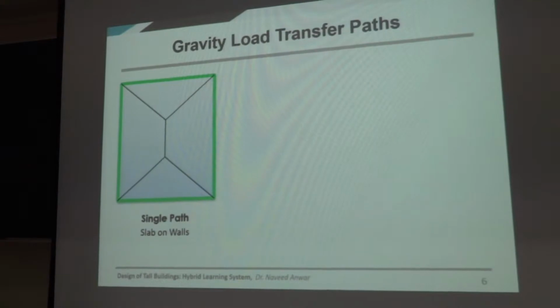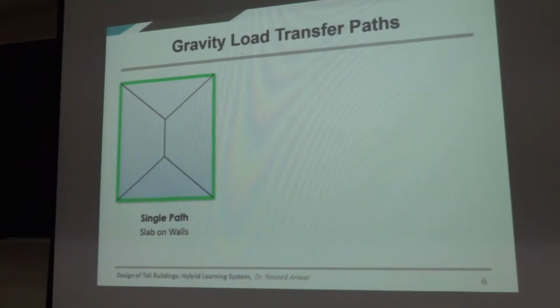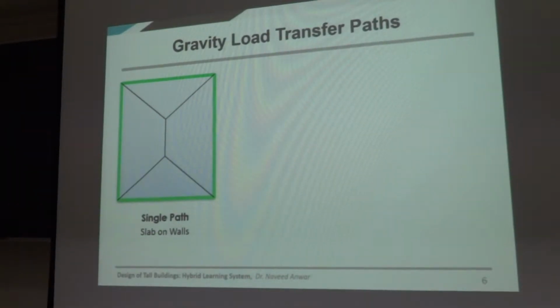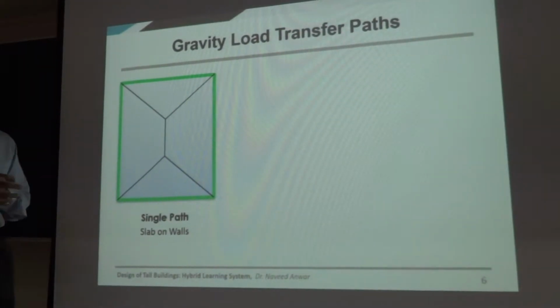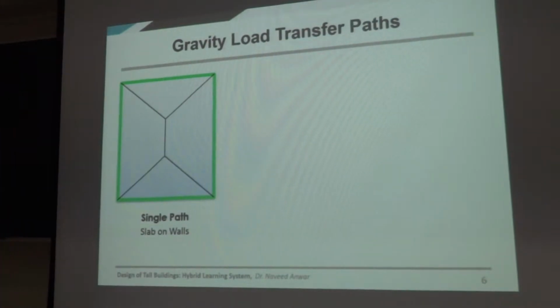That is how traditionally everybody has thought about load transfer, and that's how you calculate the load from the slab to the beam, trapezoidal load or triangular load. And if you open any book, that's what they will tell you. But we will find that this is not really the case, or this may not be the case.